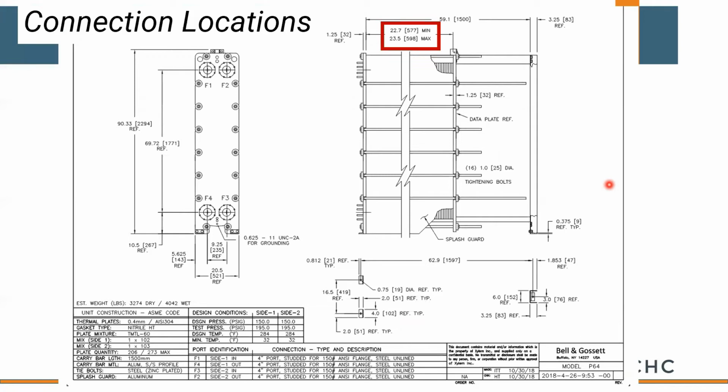Now I wanted to look at a typical plate and frame submittal drawing, just for some quick review. One of the things to touch on is the fact that between your front pressure plate, which is fixed, and your rear pressure plate that slides, in between that are all your plates, or your plate pack, as we call it. That's where all your heat transfer is occurring. You tighten these 2 plates, or at least this back plate, to a dimension. You do not tighten these to a torque.